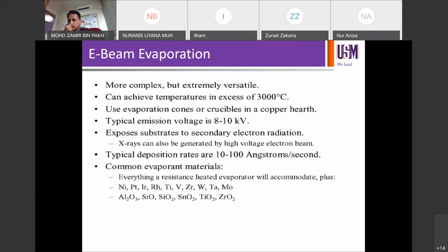You can see on the video that thermal evaporation is very simple. You just evacuate the chamber down to about 10^-5, maybe 10^-6, depending on the type of materials you want to evaporate, and then turn on the current, turn on the knob, and then make sure that your solid material melts and wets your tungsten boat, and then it's going to evaporate into gas phase, and then it's going to land and solidify on your substrate.